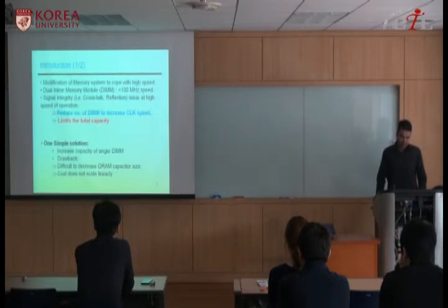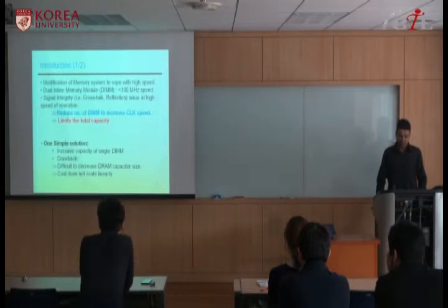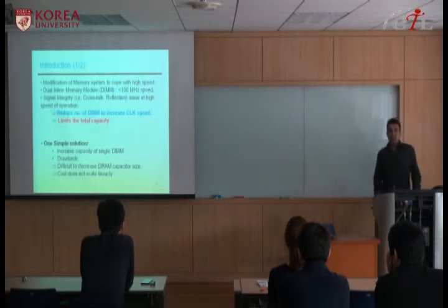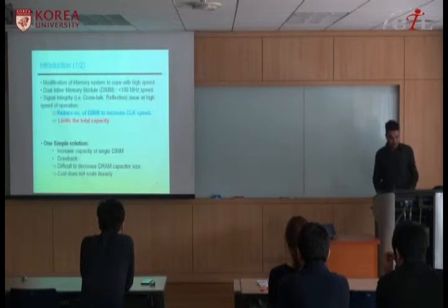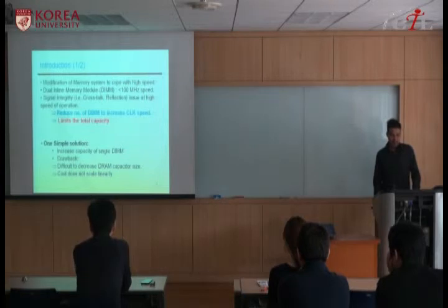For a long time we used the dual inline memory system, and as you know, the speed is less than 100 megahertz. Moreover, if we want to increase the memory, we should think about more DIMM channels. But if we use more channels, it will cause crosstalk and reflection, and that degrades the signal integrity. So people try not to increase the DIMM channels.